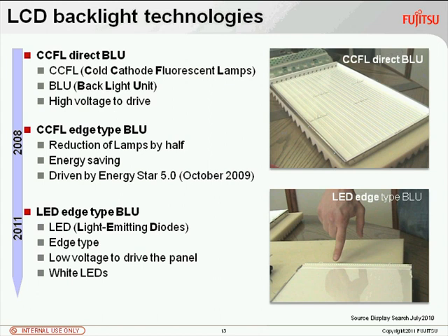And this opened the way for the LED backlight, because an LED has a very small cone of light. It is not possible to make this kind of direct backlight, but if you put it on the side, here you see a picture of the LED module. This is the LED bar. These dots are the LEDs. They put the light into the glass plate.